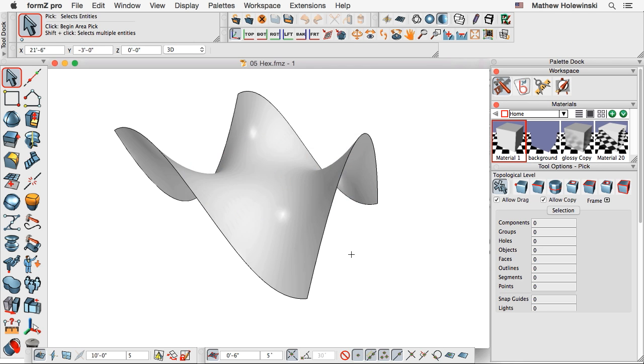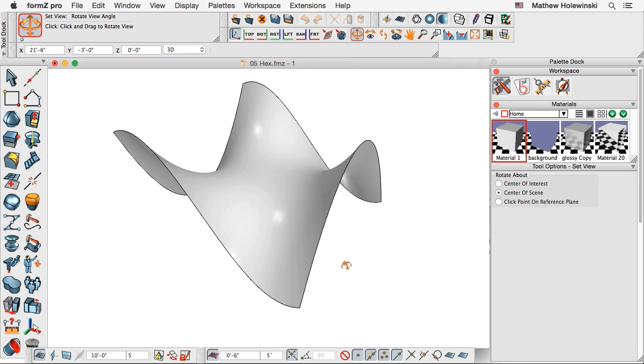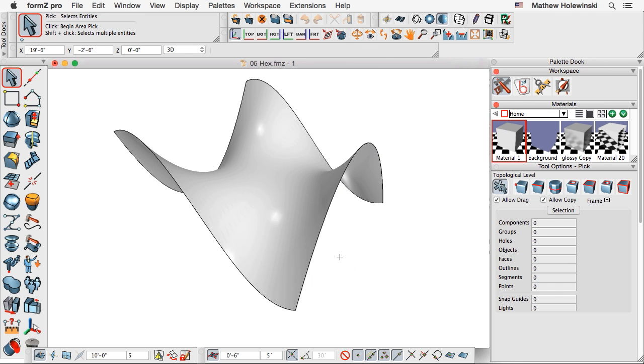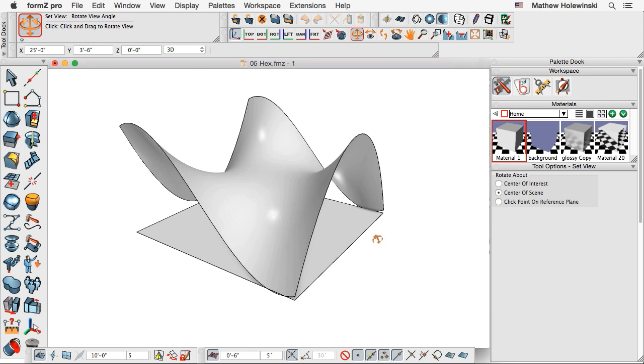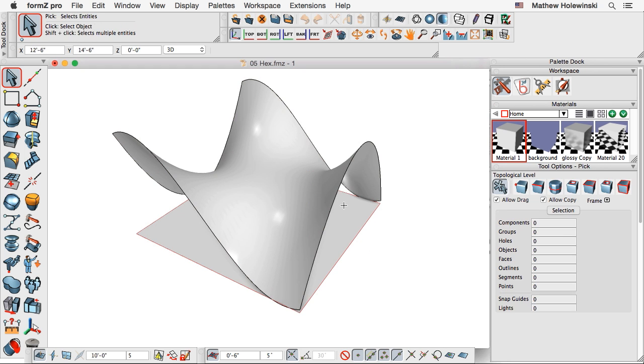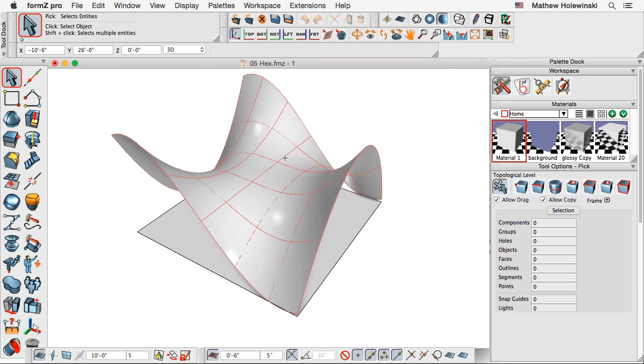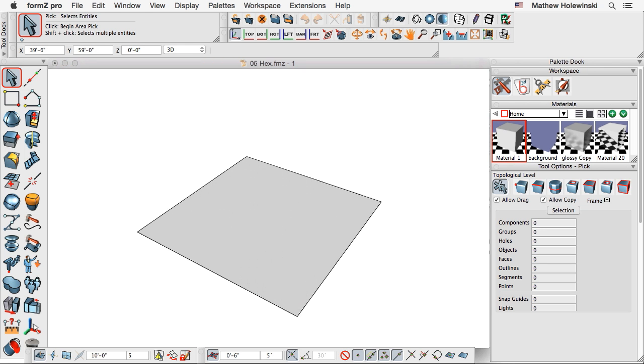We start off with our 3D form like we have, and then we're going to create our own diagram that's going to be projected onto that surface. So we start off with just a 2D rectangle, and the rectangle can be any size. Now I drew it so it's a close approximation to the size of the actual unfolded surface itself, but you can create that any size that you want.